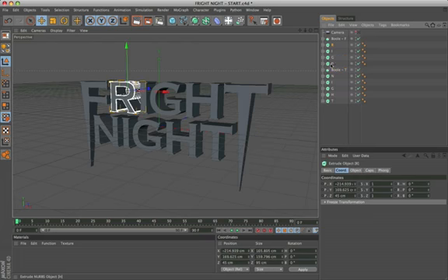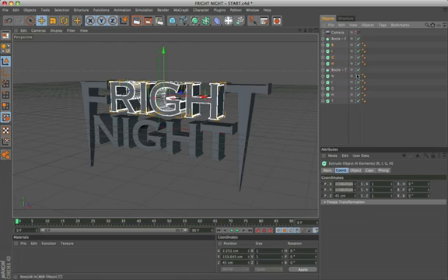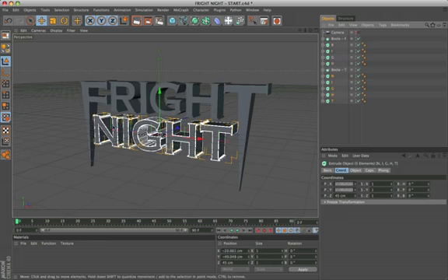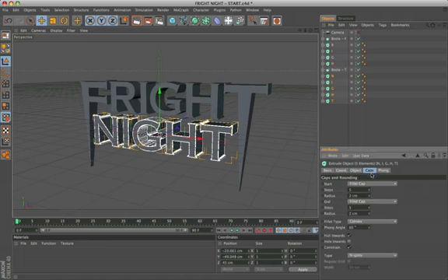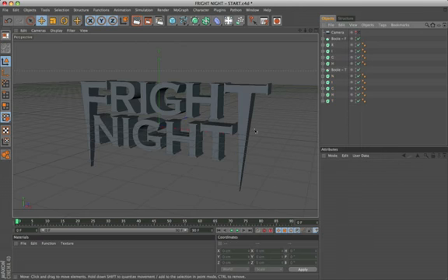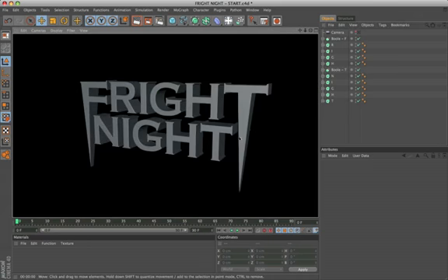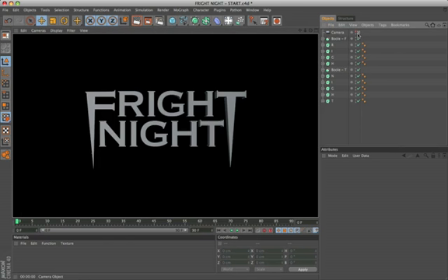Instead, for all the other letters, I applied a fillet cap. With step 5, and radius 2, on start and on end. If you want a profile like the original, the constraint check must be active. View the result. This logo, with these long and pointed letters, has a very sharp effect.